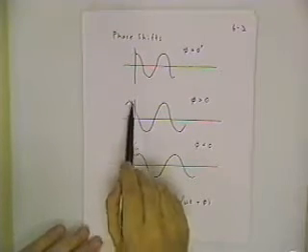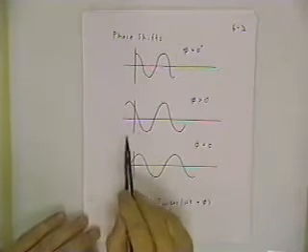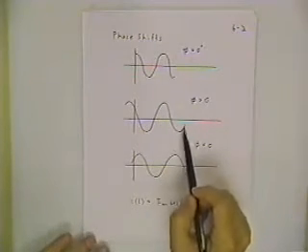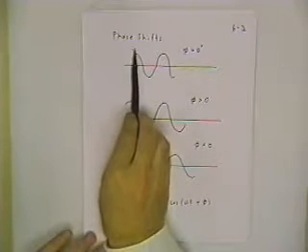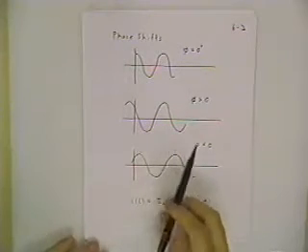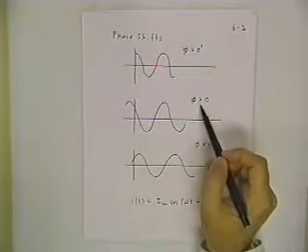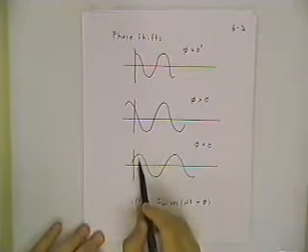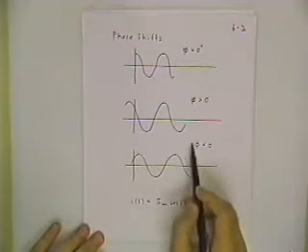Now, you could also think of that as the axis staying fixed and the cosine has slid over to the left a little bit. Personally, I prefer thinking of the waveform as being the fixed object, and then whether my phase shift is positive or negative takes this time axis and shifts it over to the right or to the left. I think it's intuitive from the number line. Positive things should be motion to the right, negative things should be motion to the left. So compare that with a negative phase shift. If you started off with the time axis here and you shoved it over to the left a little bit, that would be a small negative phase shift.